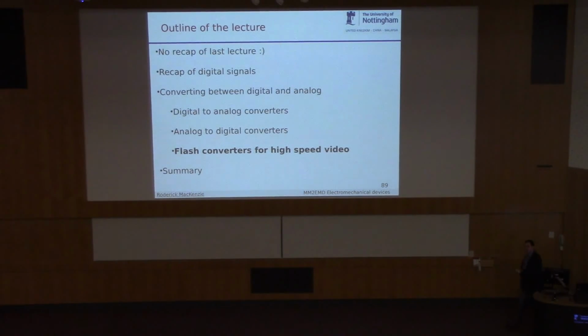Now, at the back of this lecture, I've got a camera, and it's recording me in HD. Across this screen, there might be 700 pixels, and above there's 400. And each one of those pixels is going to need an analog to digital converter. You can't have a video image waiting and counting up in the R2R ladder, because by the time it's gone through its conversion process, I'll have moved and the picture will be all blurry.